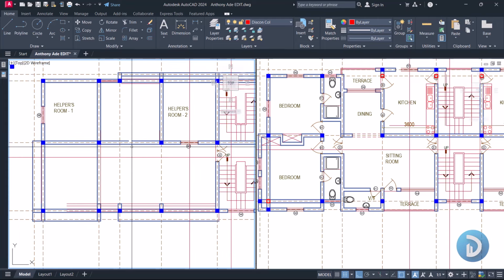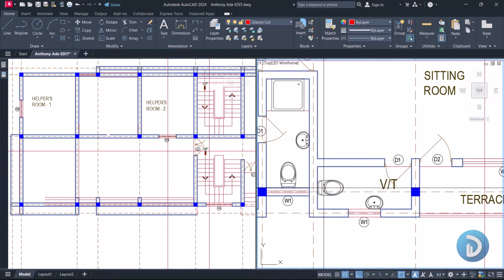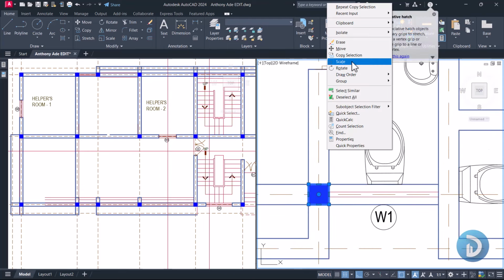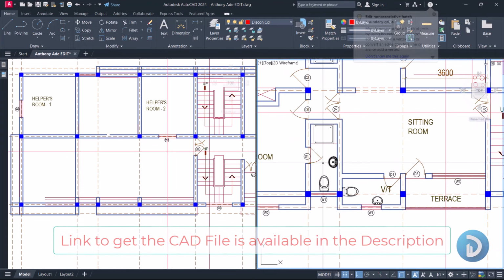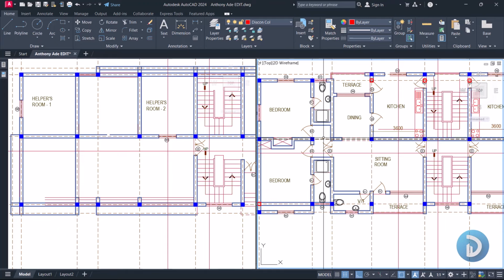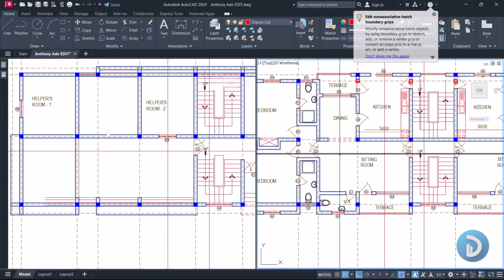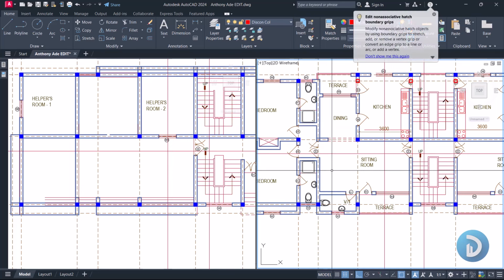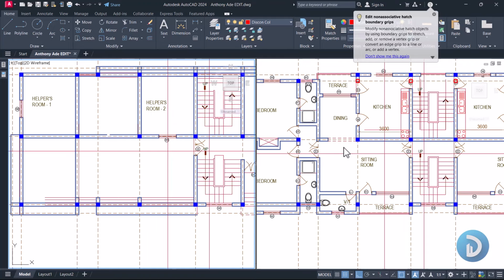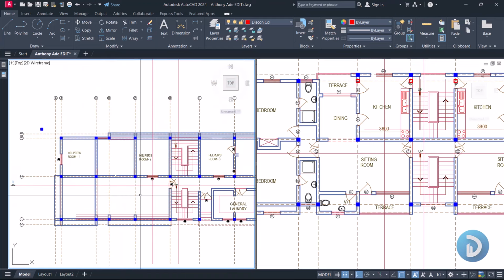Then we have a decision to make. Okay, we have two options here. It's either we get to run a beam on this very part. Yes, because if you observe, we have a larger sitting room here. Okay, so it's either we get to run a beam at this very point, or we can decide to stick with the same beam arrangement that comes from grid line C.